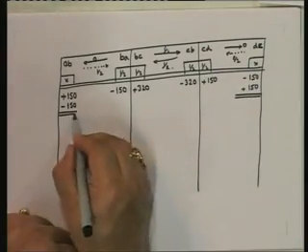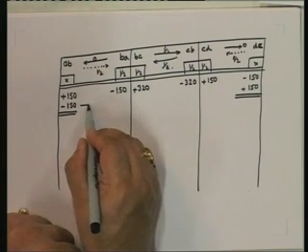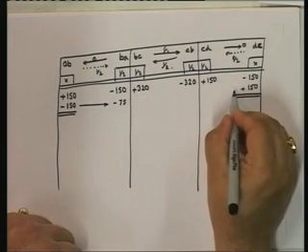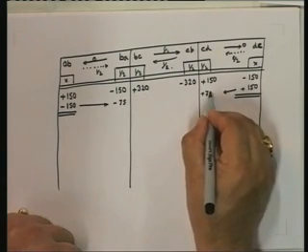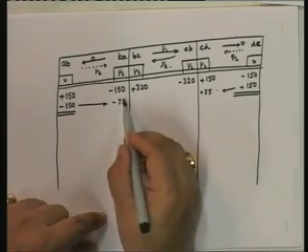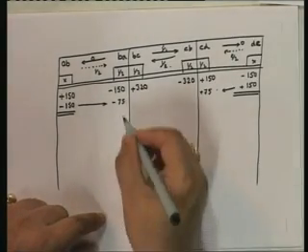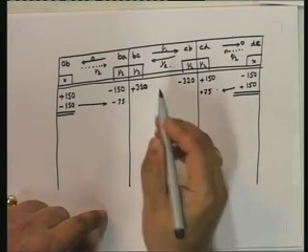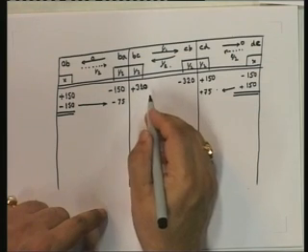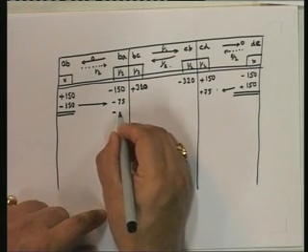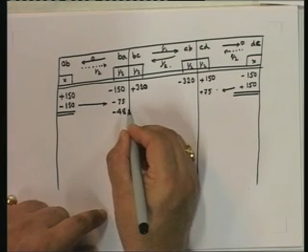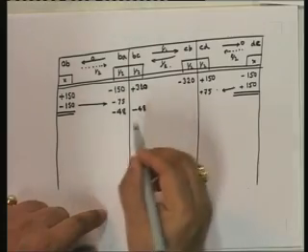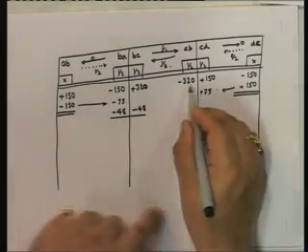These are finished, and all that we do is take this here and put minus 75 here and plus 75 here. Now this is the one that we need to distribute. So if you look at it, 225 and this is 320. So the net unbalanced is plus 95, so minus 95 has to be distributed. So we do minus 48, minus 48. Similarly over here we do the same.